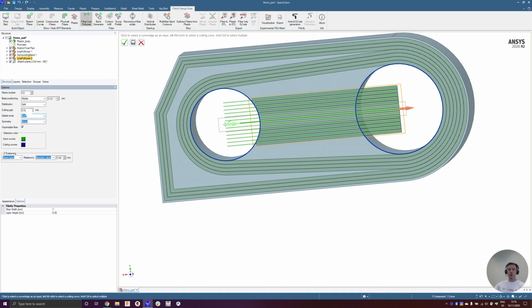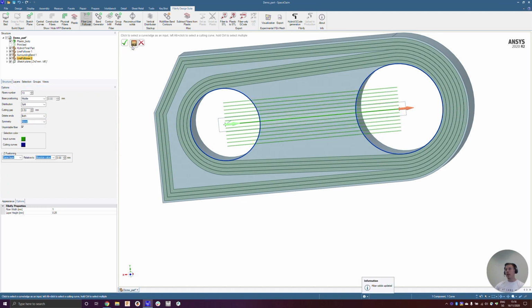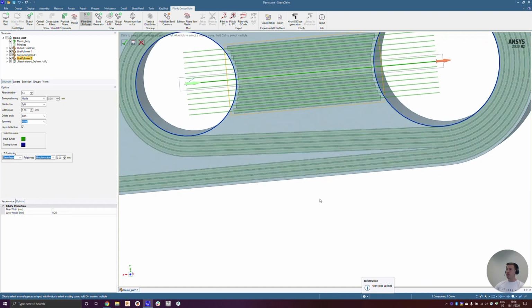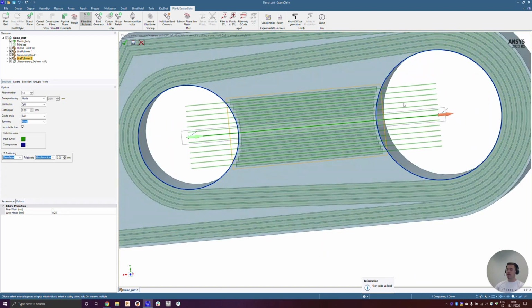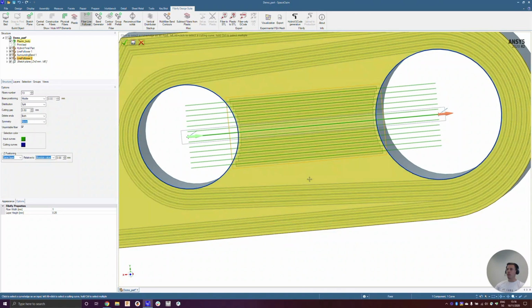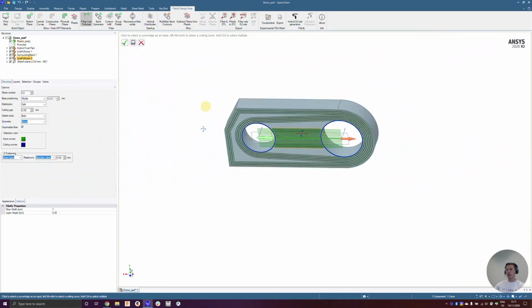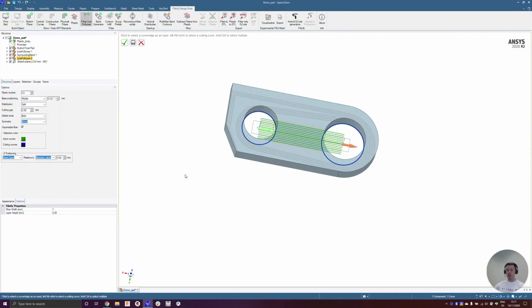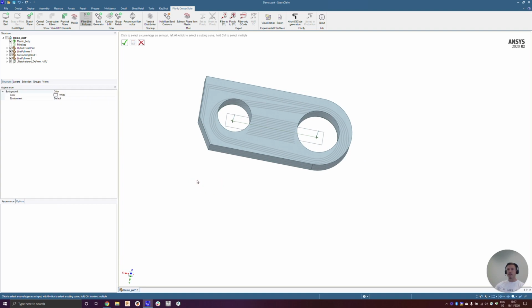We can also implement a cutting gap of, let's say, 0.5 millimeters, update the changes, and as you can see now, we have now cut our prefab on both of our cutting curves with a cutting gap of these 0.5 millimeters. Perfect. So again, press Escape to cancel the selection and S to leave the tool that we are currently in.